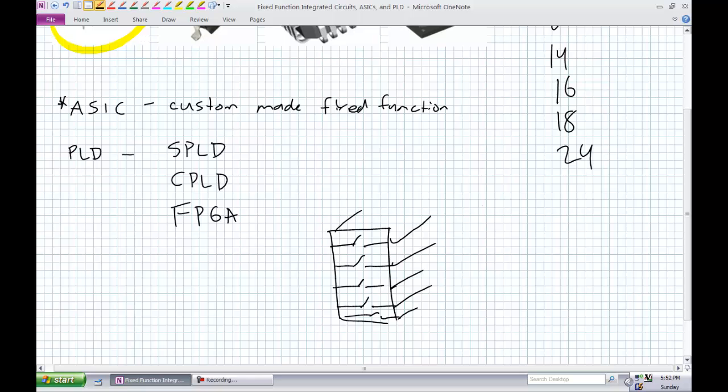So when I hand you a dual inline package switch, you have to know that an open switch has incredibly high resistance across it. A closed switch should have incredibly low resistance across it. And don't be the guy that takes those things and puts them into a single column, because, as we said, those rows of 5 on a protoboard are electrically connected.